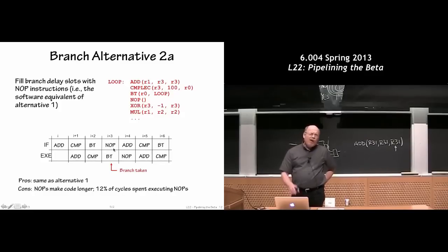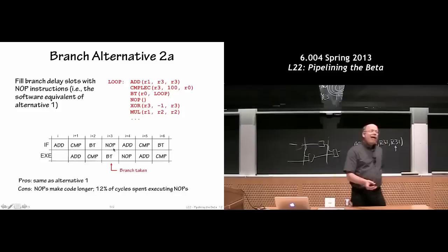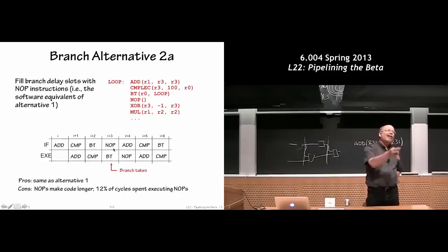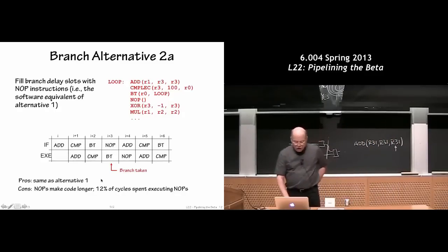Okay, well, you say, SMOP, small matter of programming. Instead of adding hardware, why don't we tell the software guy to go off and simply put in no-ops? Well, now your programs are longer, so all of a sudden you have all these no-ops filling up your memory, and instead of synthesizing them in hardware where needed, we put them into the actual program itself.